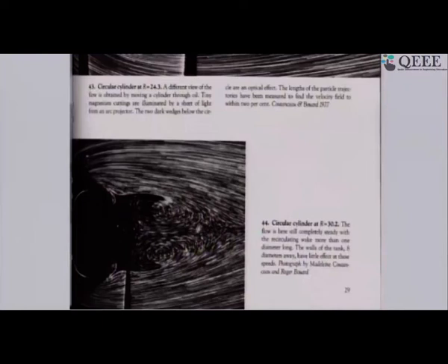You have a much bigger wake, which is now bigger than the size of the diameter of the cylinder. The same thing is happening, and the outside flow is still there. The front part I'm not discussing again, because at the front nothing has changed. The front part is pretty much the same as what we had seen in the first picture.